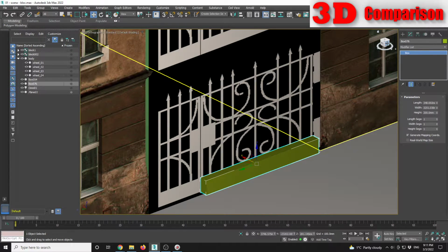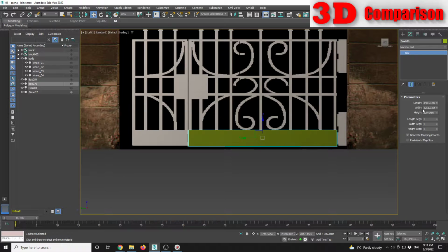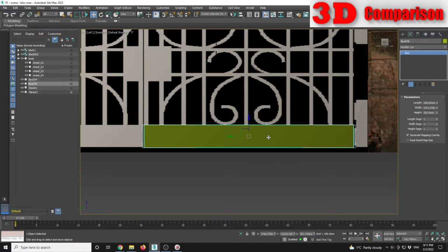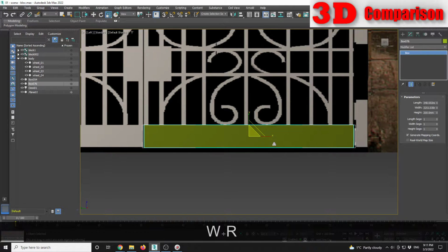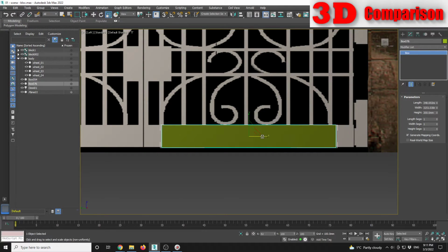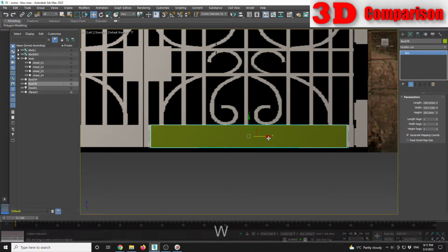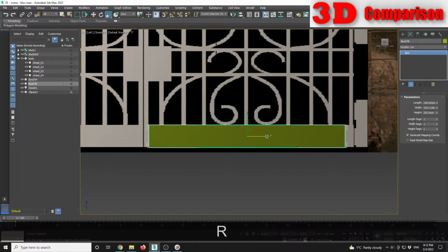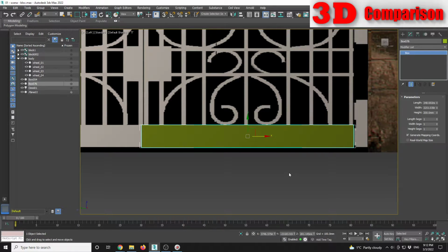And now for the other elements, I see the length and the width dimension over here. I can either go between scaling and moving to define this, so by scaling from the middle like this, have it reposition, and after that scale it again, and maybe again reposition that. But if you want to have, let's say, more precision, you can always convert this to edit poly.